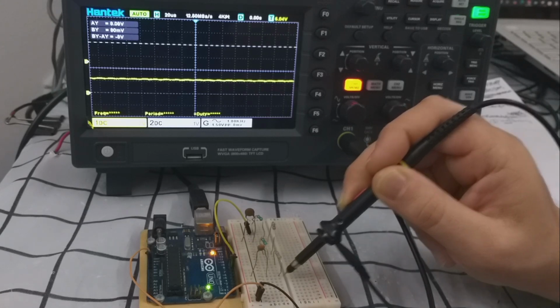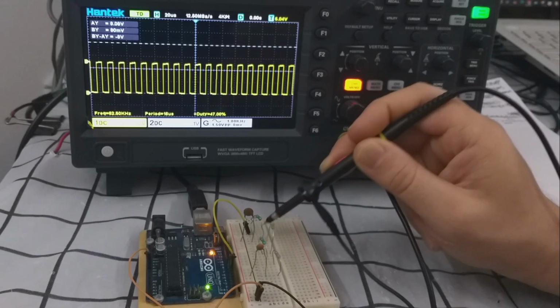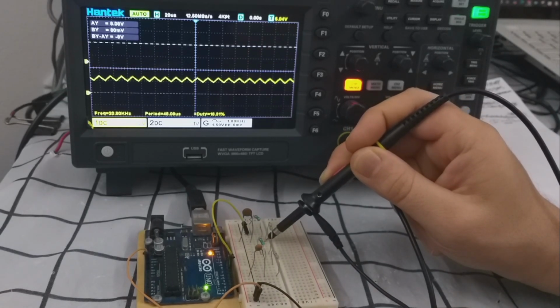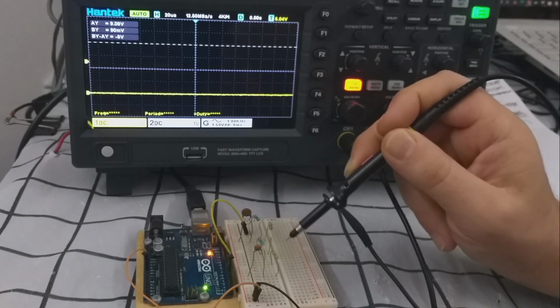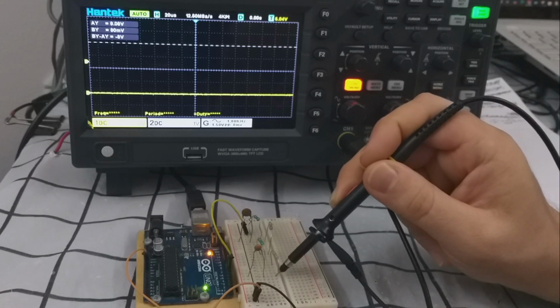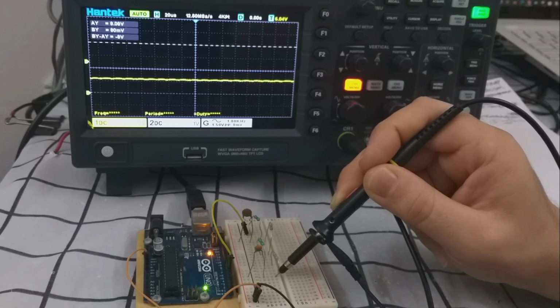Okay, so again, here is the pure PWM input. Here is the first stage where we still can see the ripple, not very clear. So when I added the second stage, you can see the output is much cleaner now. So with this, I can see that this DC voltage is ready to be buffered and used for the other application.